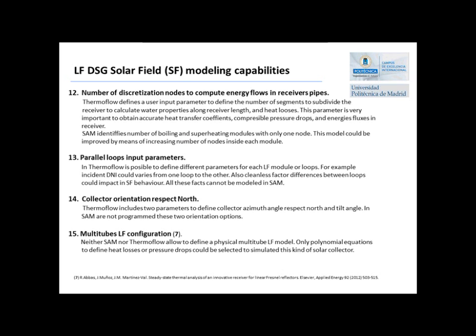Multi-tube linear Fresnel configuration. Neither SAM nor Thermoflow allow defining a physical multi-tube LF model. Only polynomial equations to define heat losses or pressure drops are input by the user to simulate this kind of solar collector.